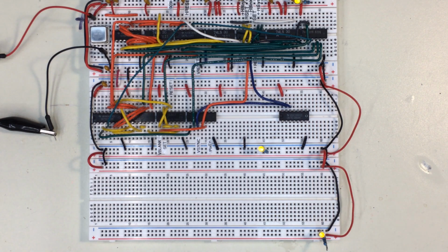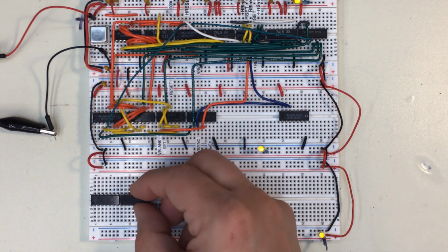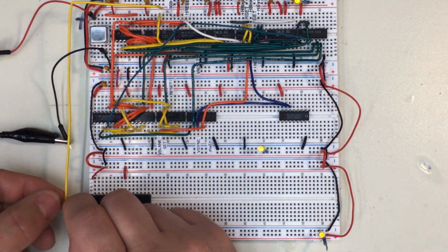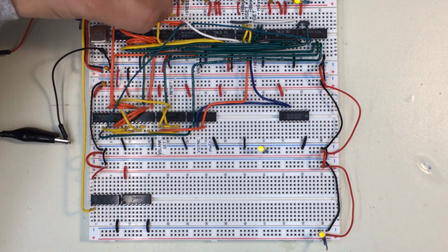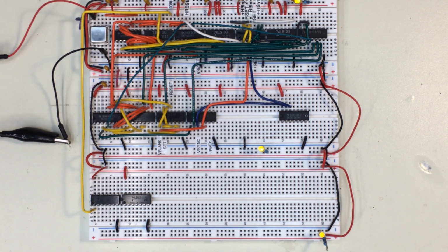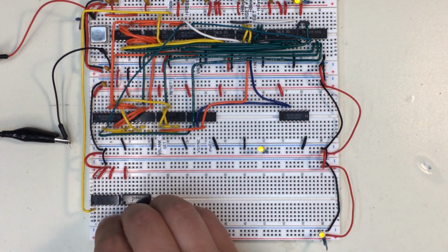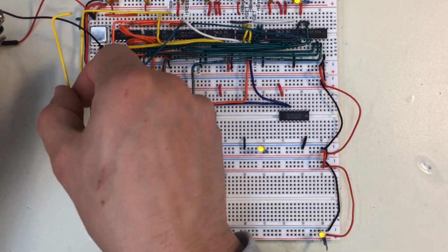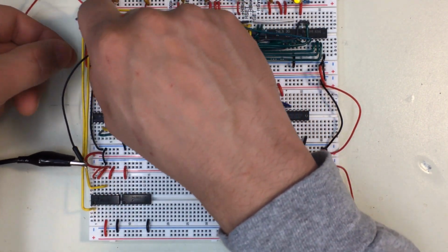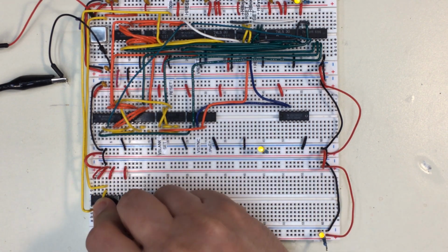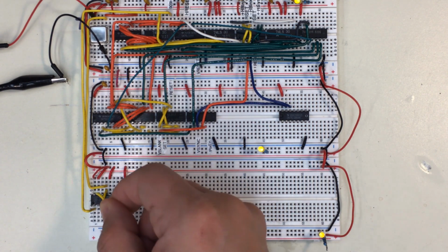So let's build it. Let's get the 74LS74 and 74LS02 chips populated, and then hook them up to power. And then we tie not H reset into 1 clear to sync the circuit to line boundaries. Next, I tie the extra clear and preset lines high. Now I bring the 14 MHz clock into 1 flip-flop. Then I cross-connect the flip-flops on the clock lines and hook 1Q to 2D.